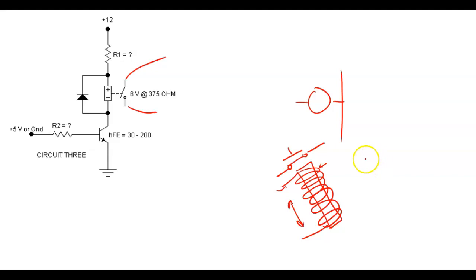So some of your contacts are normally closed, and these are drawn below. Normally closed would open, and normally open would close when we put power to it. So now we have an electrically controlled switch. Now we can automate things because now it's taking it away from me deciding when circuits are turned off and on, over to electrical control of when it turns off.